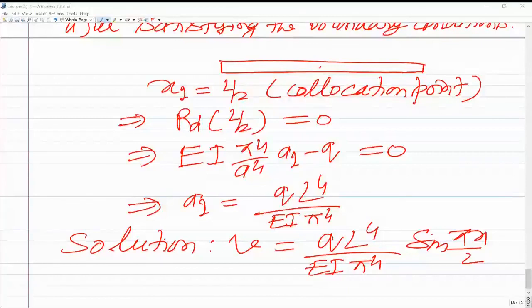but the use of the Galerkin method is more common, because once you have your assumed approximate solution after satisfying the boundary condition, it is easy to know what the weight functions w are. The most common method is actually the Galerkin method, because weight functions are easily identified.